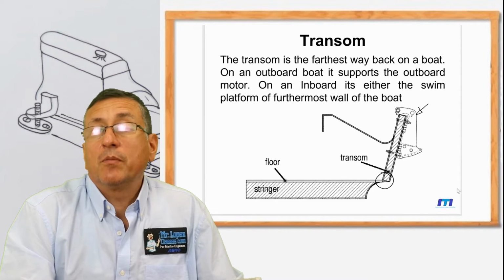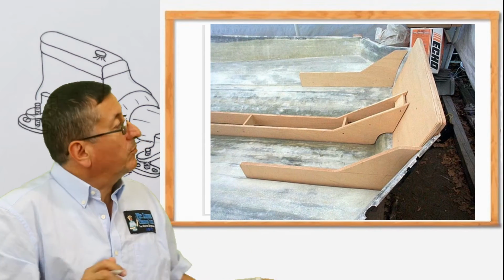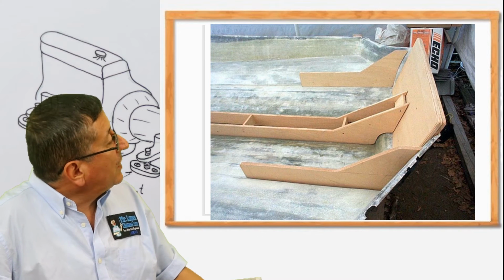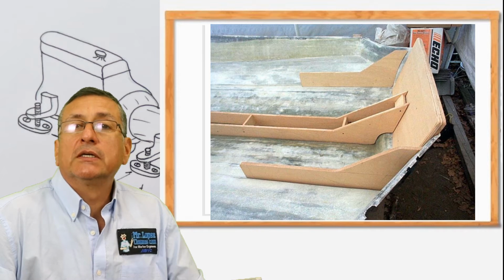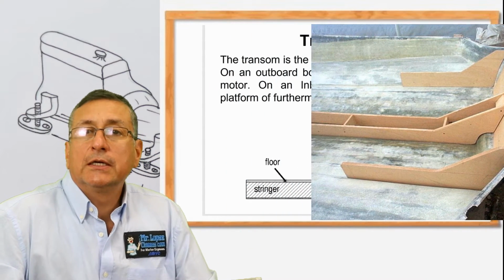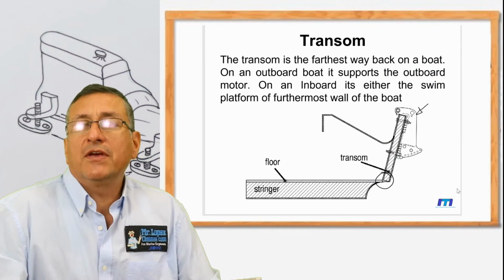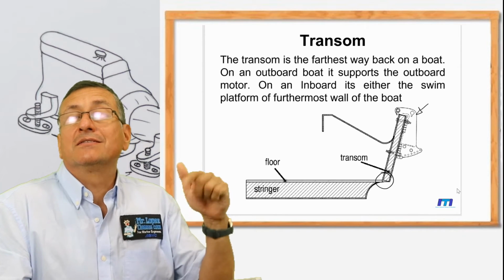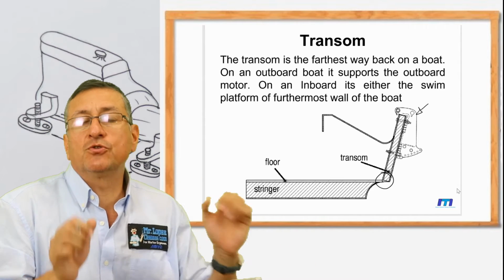Install it at the moment that you fabricate the new transom. I recommend installing those reinforced triangles inside of the boat in order to better support the new transom. This is great because right now the transom is properly supported. Yeah, the transom is critical. It's a critical part, especially if on the transom you have the outboard or the stern drive connected over there. That transom should be strong.